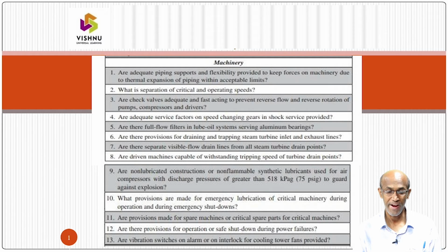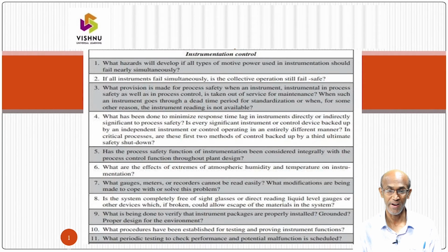Are provisions made for spare machines or critical spare parts for critical machines? Are there provisions for operation or safe shutdown during the power failures? Are vibration switches on alarm or on interlock for cooling tower fans provided?